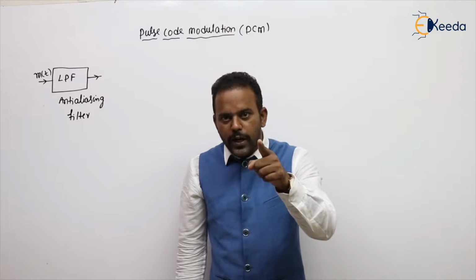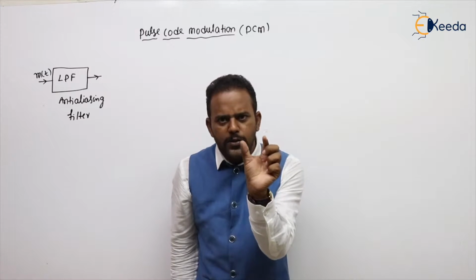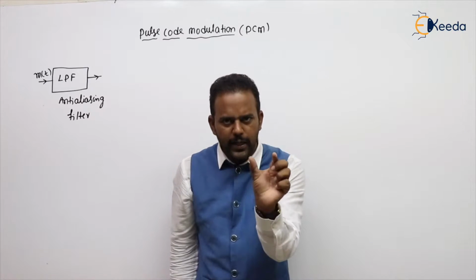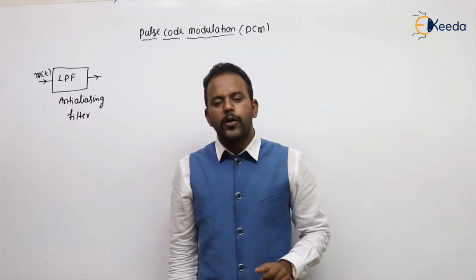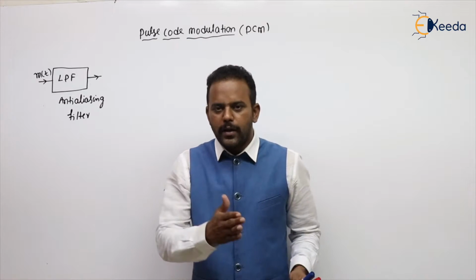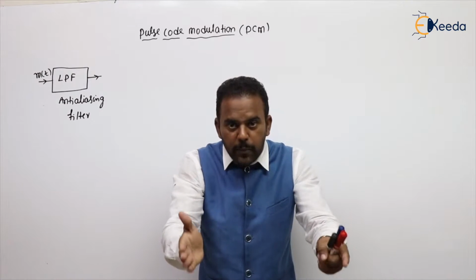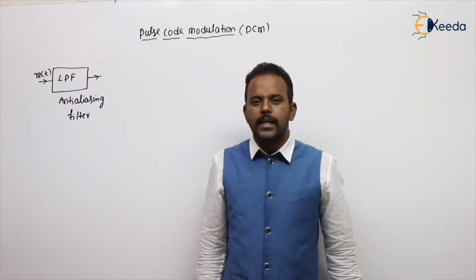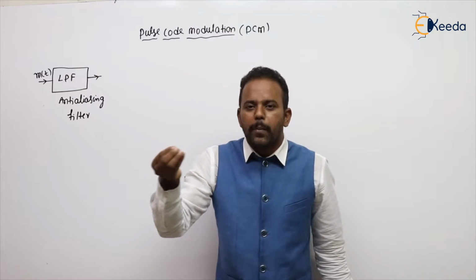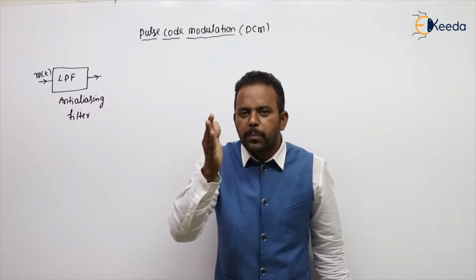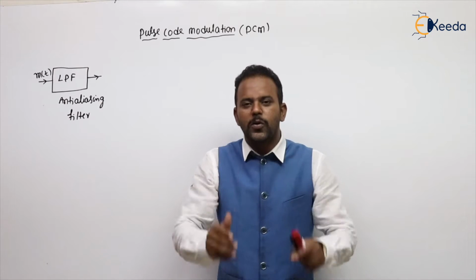In the review of Fourier transform topic, I gave that if you take a small rectangular pulse of width Tb, and calculate the Fourier transform for that, you will get a bandwidth of infinite. But important frequencies are up to a certain value only, which means we need to limit up to there. The meaning is, general practical messages have frequencies up to very large, but the significant components are only up to a specified value. So we need to send those only.